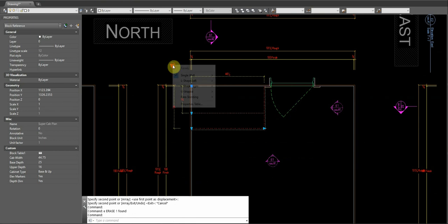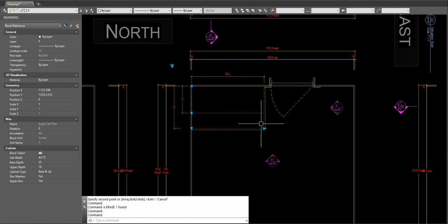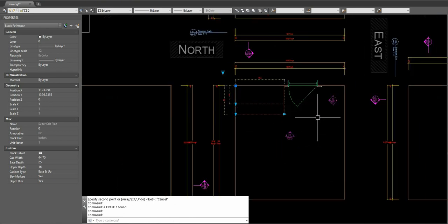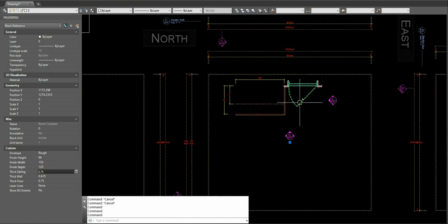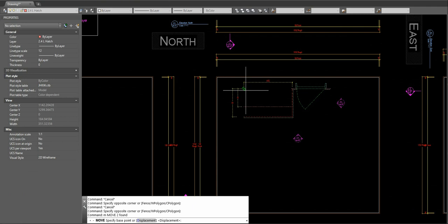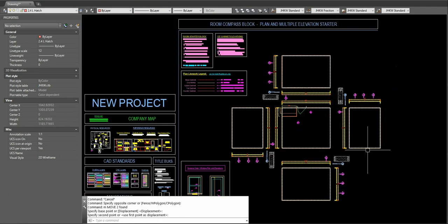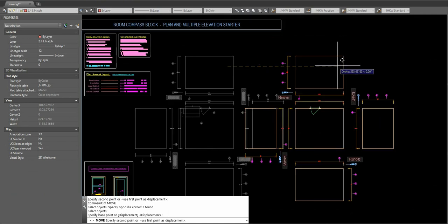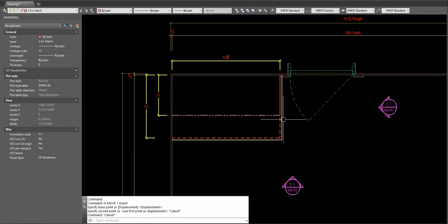It's all about versatility, yada yada yada. So yeah, I'm thinking out loud, trying to figure out how to work with this here. Let's change the room width to 150 and the depth to 120. This room block has a base point in the middle, so as I update these, it'll move the room around. But hopefully you started with the room dimensions and didn't just start drawing cabinets in willy-nilly.